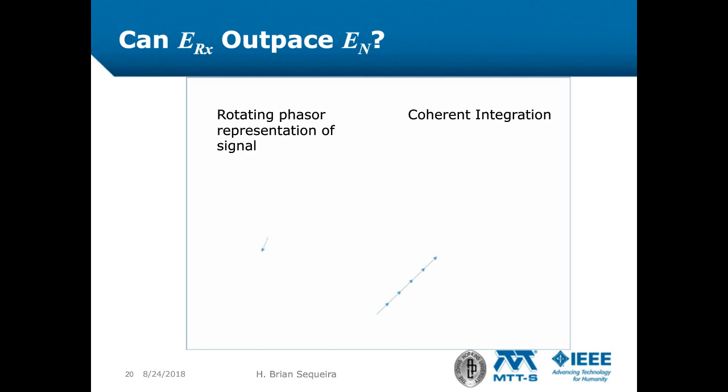But suppose that noise is sampled over a 30% longer duration than the signal. Then the required SNR would be achieved after 28 samples. Inherent in this description is the time taken to accumulate sufficient energy. It is aptly called the integration time. Stroboscopic sampling is known by the term coherent sampling, and the time interval over which it extends is known as coherent integration time or coherent processing interval.